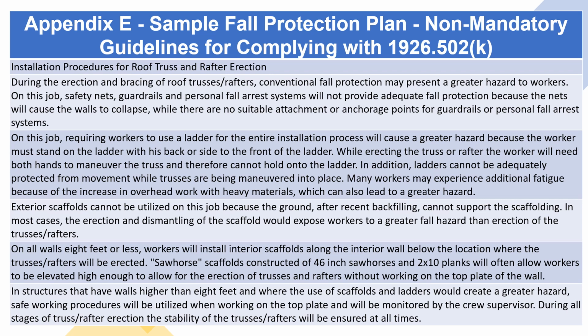On this job, requiring workers to use a ladder for the entire installation process will cause a greater hazard because the worker must stand on the ladder with his back or side to the front of the ladder. While erecting the truss or rafter, the worker will need both hands to maneuver the truss and therefore cannot hold onto the ladder. In addition, ladders cannot be adequately protected from movement while trusses are being maneuvered into place.